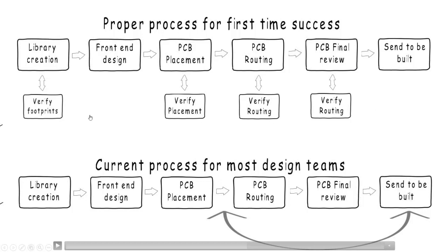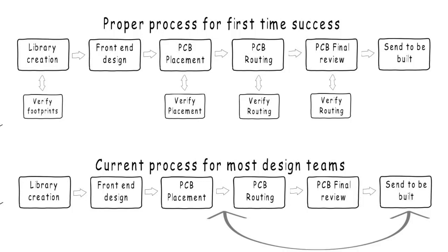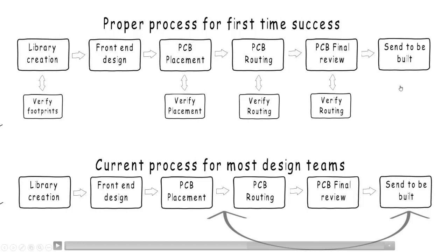Now, if for some reason you're producing low volume designs, you're only doing a couple a year, sometimes it doesn't seem justifiable to spend the money on a DFM tool. You can at least partner with someone that has a DFM tool that can verify your designs, again, as the phases continue along. So don't wait until the end to do this.